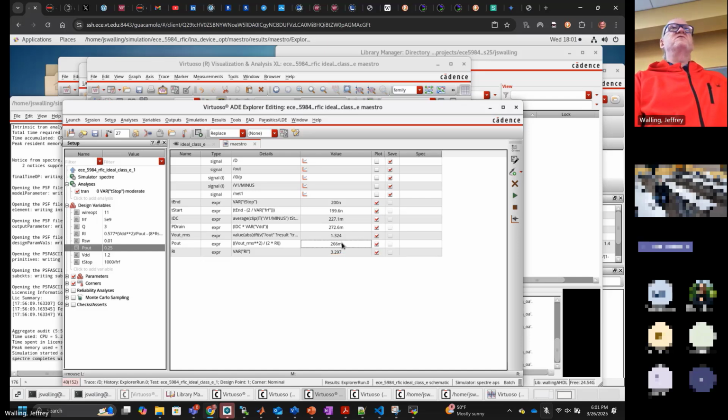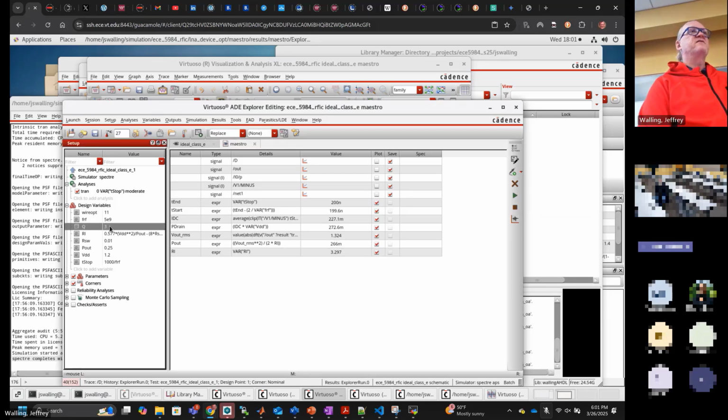Some of that could just be thermal dissipation, but some of it could be leaking into harmonics and contributing to the harmonic content. Of course, I also set a relatively low quality factor here, so that plays a role in this. If you set the quality factor higher, it's going to take longer to settle also.